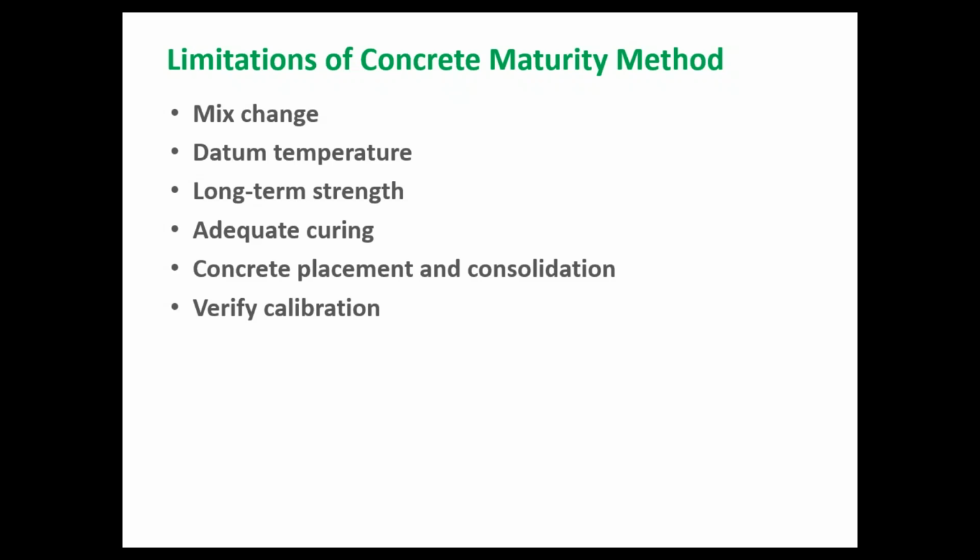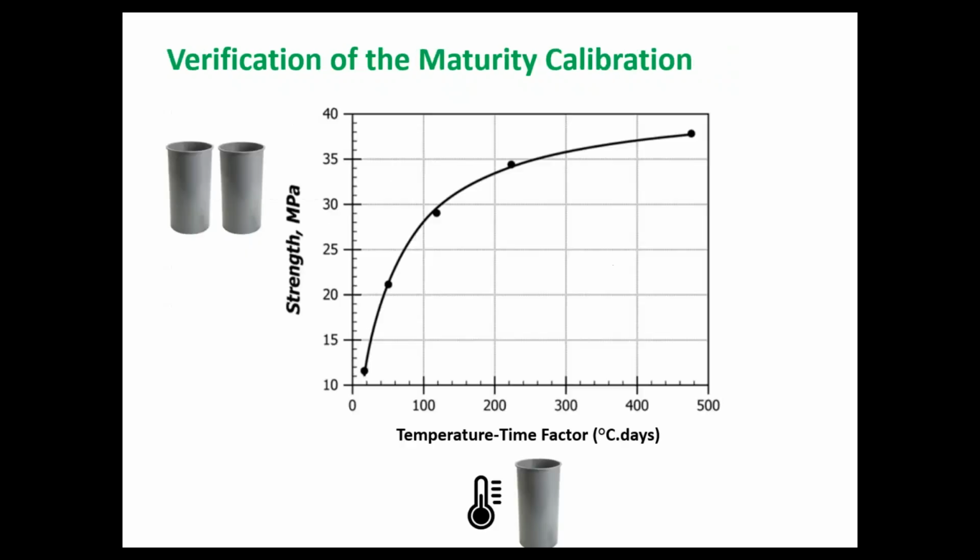Monitor concrete strengths and verify it with field cured cylinders. And when you're confident, you can completely eliminate field cured cylinders. And the verification is simple. You basically cast 3 cylinders from your mix that is delivered to the job site.